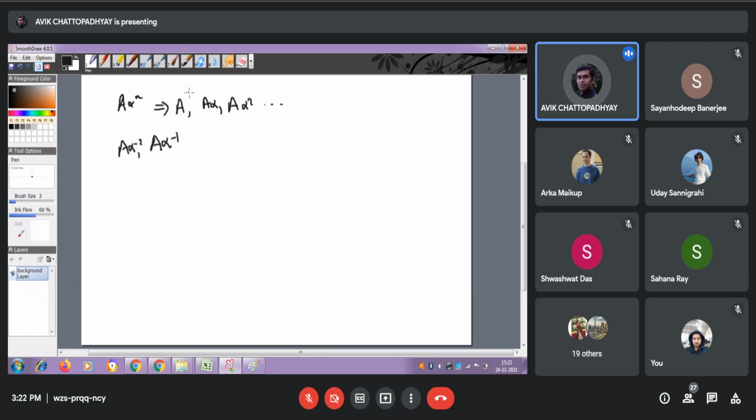So for the first case, it is just a right-sided or right-handed signal, and the second case is a both-handed signal. So you have the values for the past instances, the present instant, as well as the future instances, in all directions, for positive and negative values of n. In the first case, you have only the present and the future, so only for positive values of n. Now, suppose a alpha to the power n starts from n equals 0 and tends to infinity.